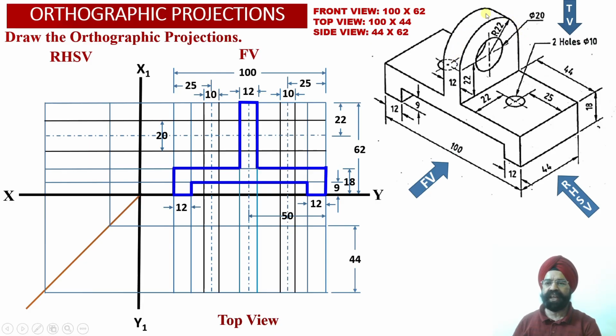So since this is a curved surface which is being projected as an apparent shape in the form of a rectangular shape over here, so this projection which we have obtained above the center line, even though it appears as a rectangular projection, it is corresponding to the circular portion of the semicircular arc over here. So this is the apparent shape projection over here.